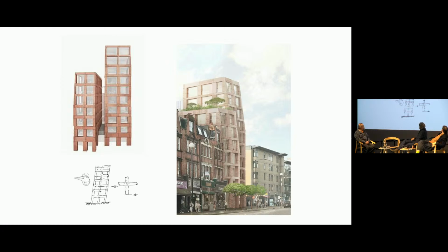So, this is a building composed of 3 separate blocks, two narrow towers and another block at the back. The access to these buildings is an external staircase, so a lift shaft and a service riser and a staircase, which are unclosed, and they sit between the 3 towers, and so the building has no structural core. Typically, as you probably know, you build a building and you have a lift shaft. The lift shaft is the thing that stops the building from falling over. There's nothing like that here.